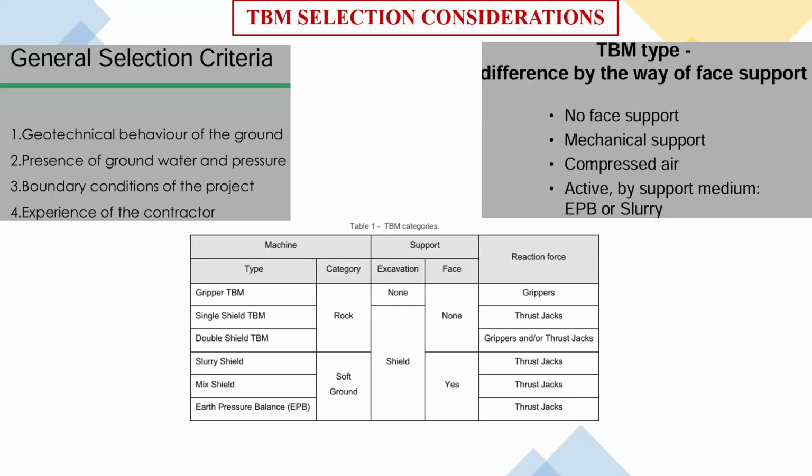Yeah, so my understanding is that full closed mode is when your full EPB is working, when you have sufficient muck in the excavation chamber that is balancing out the pressure. And before that, maybe a little muck or some compressed air is maintaining the pressure. Yes, when you are working in the TBM intervention part, you apply a minimum air pressure, because the TBM is not getting face pressure from the ground, so it applies a minimum air pressure, or it depends on how much muck is there.